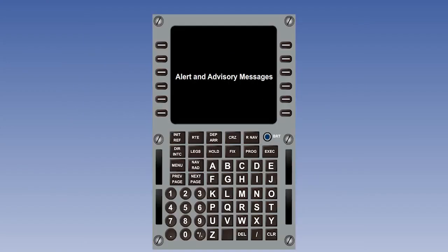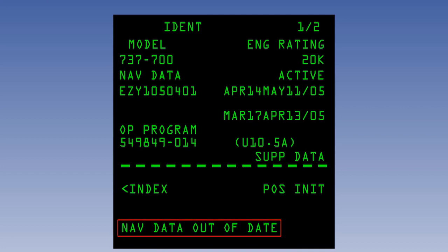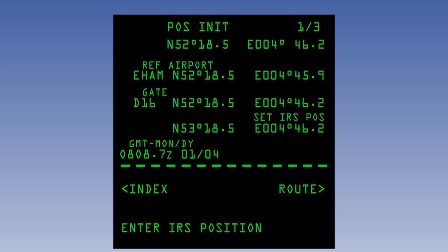However, the scratch pad also has a second use. The computer is programmed to pass relevant information to the pilot should it be necessary. These are called alert or advisory messages. Alert messages have the highest priority and they identify a condition which must be acknowledged and corrected by the crew before further FMC guided flight is advisable or even possible in some cases. Advisory messages have lower priority and inform the crew of the CDU entry errors or system status.